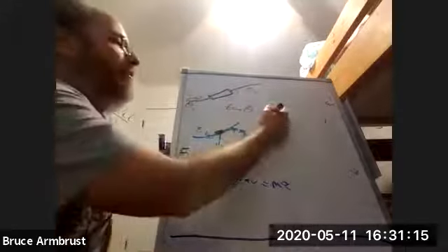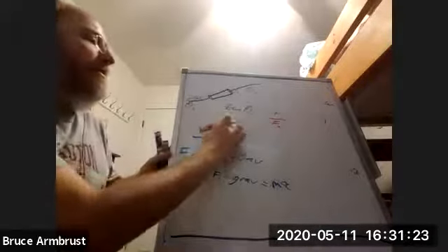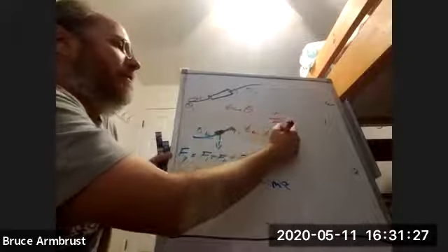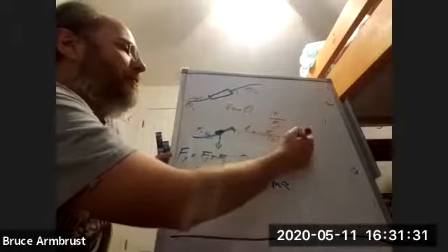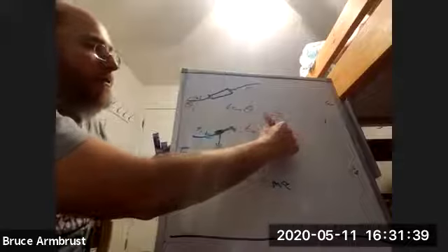Over whatever the horizontal force of this tension is. I'm going to call it F sub x. And then theta 2, similar story, except it's going to be F2 over that F sub x. But like I said before, those F sub x's we know are the same because it's not moving left and right.